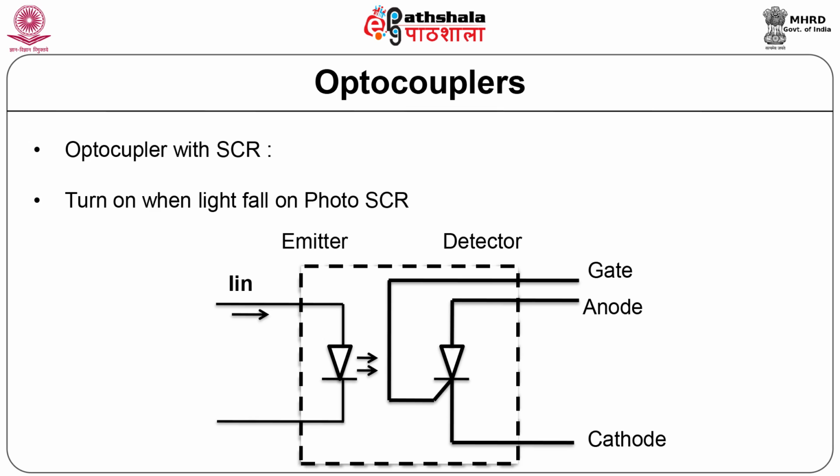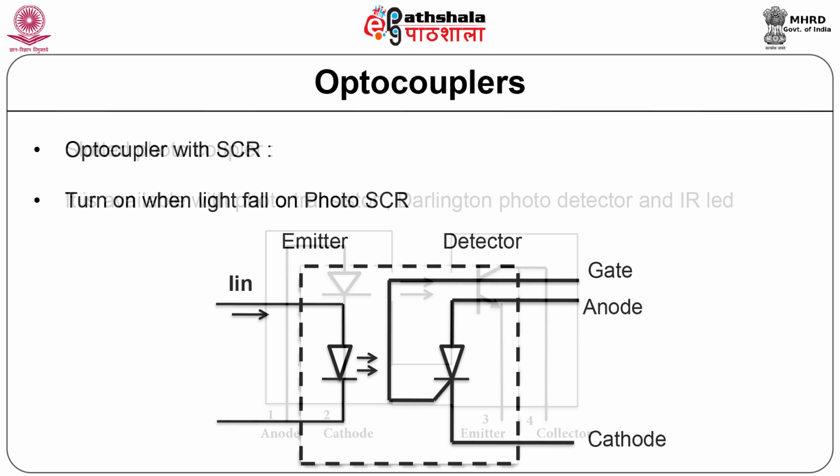To turn the system off after being triggered on, a single pole single throw normally closed switch for circuit reset can be inserted in the supply voltage path to momentarily remove the supply voltage after the input pulse returns to 0. The momentary opening of the switch turns the SCR off and sets the system to its standby condition.